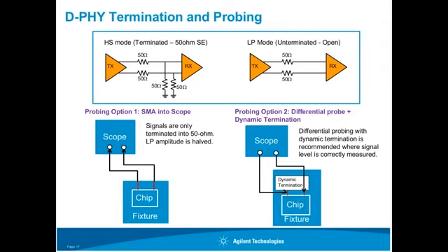So memory is associated with the trace capture, right? Scope is an analog instrument. When it saves the waveform, it saves it with many bits, and because of that, we are limited by how long a trace we can capture. But on the analyzer, we only capture zeros and ones, so the analyzer can actually capture a really deep trace for analyzing your protocol. And the other thing is the analyzer can have a hardware trigger that can trigger on specific protocol packets. This is something not available on the oscilloscopes.